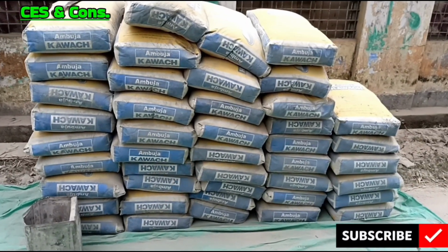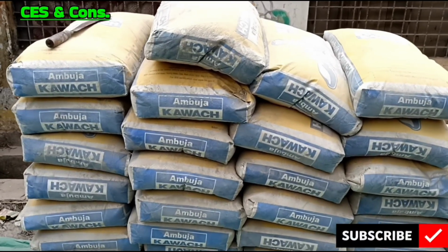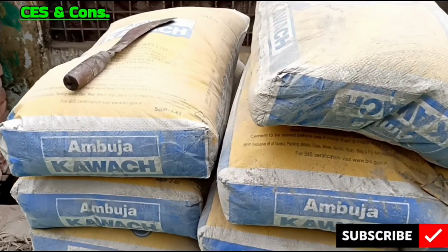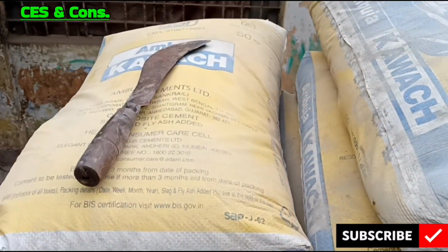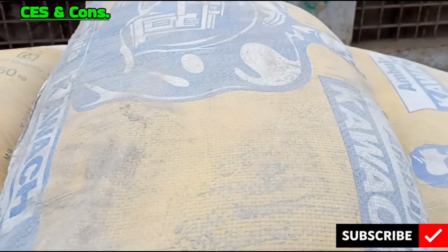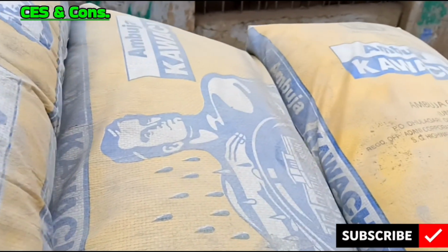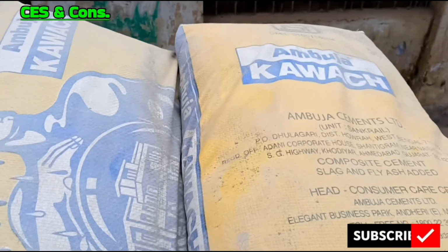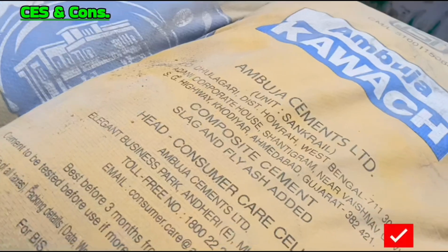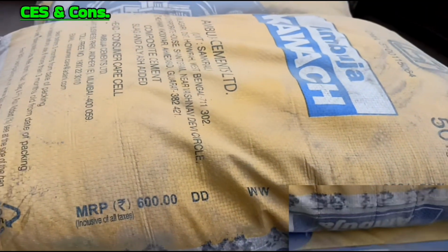Now this is cement. There are different types of cements available in the market. But which one can we use for the RCC work? For RCC work, cement is the most vital ingredient. Indian Standard Code of Practice specifies detailed requirements regarding its type, grade, quality, storage and testing. I am stating here in detail. IS code specifies the types of cements generally permitted for RCC work.